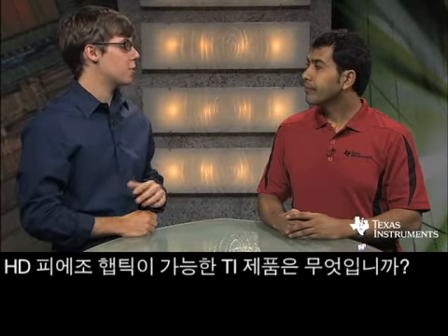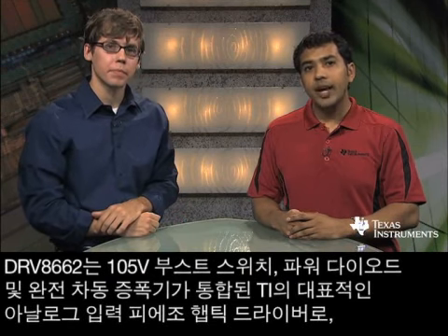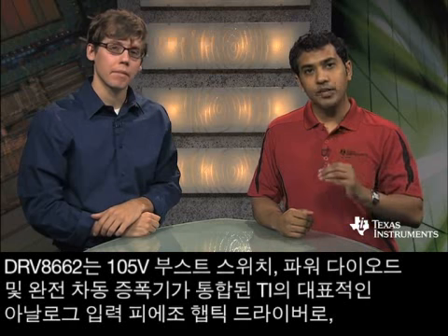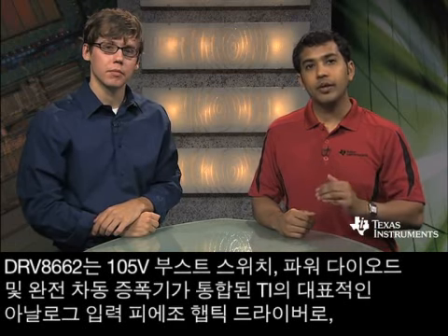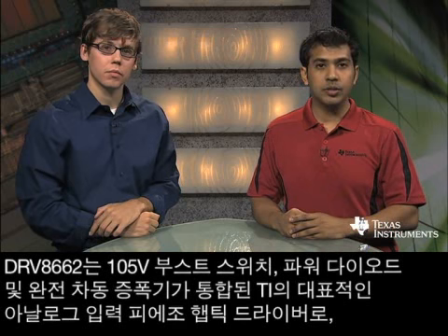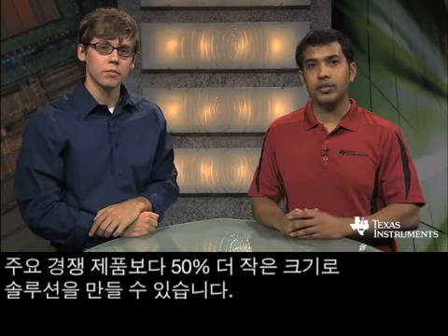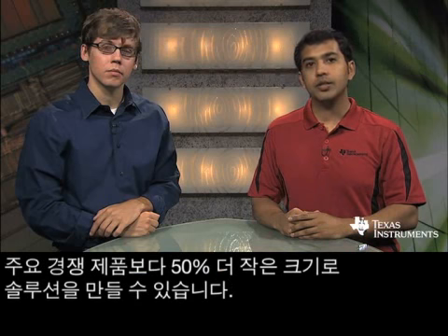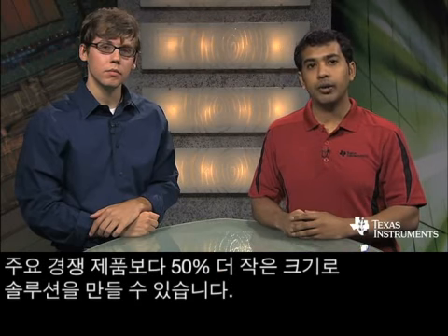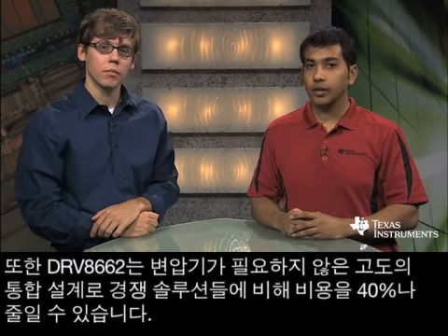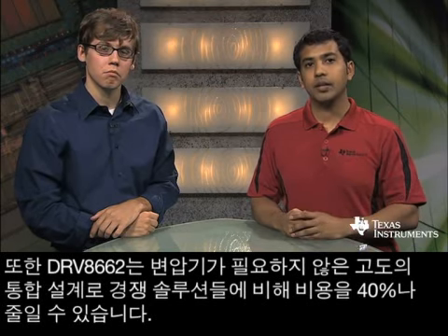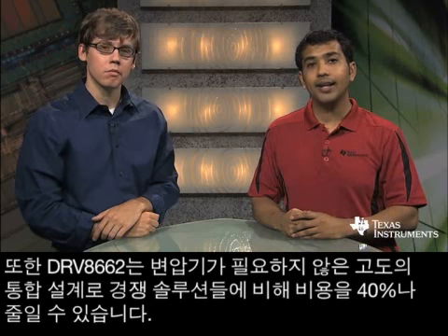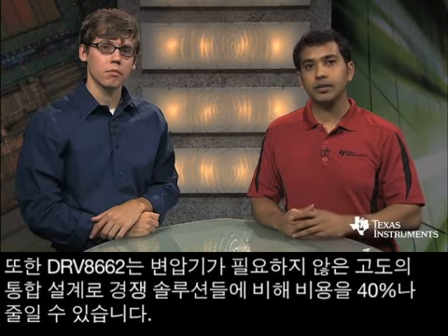So what are some of TI's products to enable high-definition piezo haptics? The DRV8662 is TI's flagship analog input piezo haptics driver and features an integrated 105-volt boost switch, power diode, and fully differential amplifier, resulting in a solution size that's 50% smaller than the leading competition.